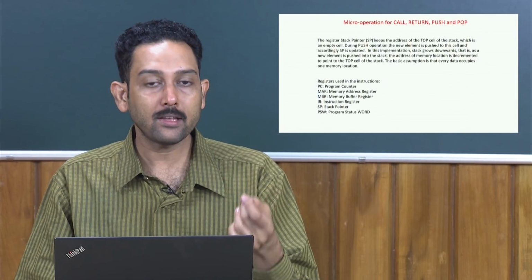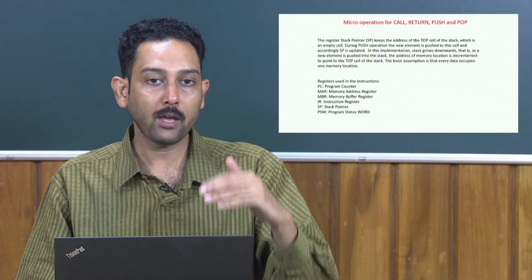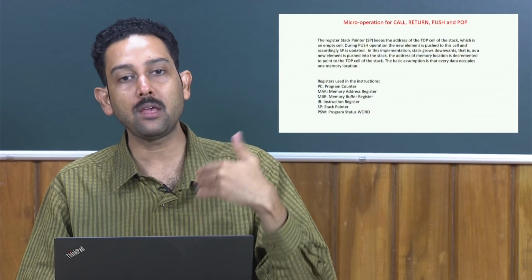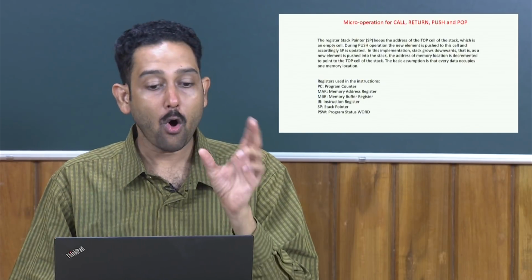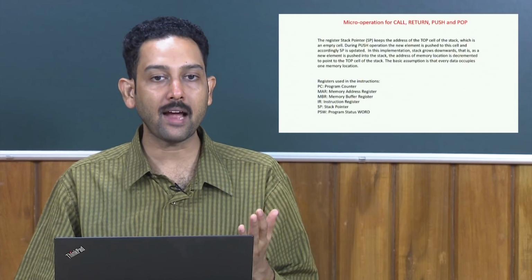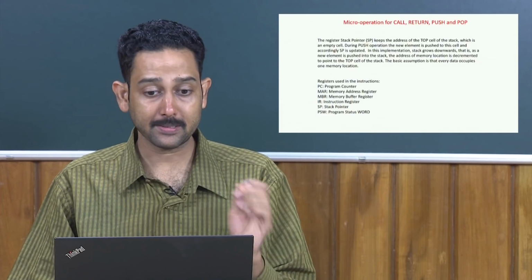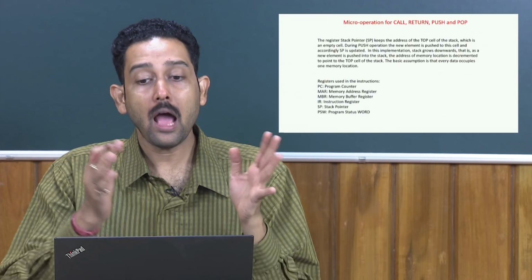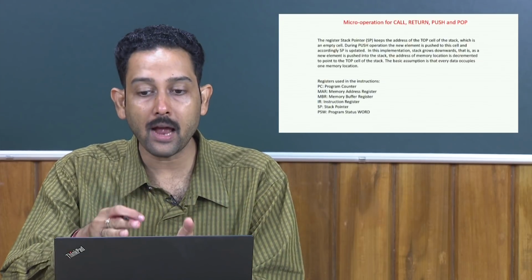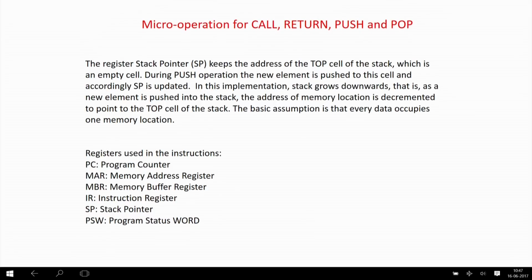If you want to call, then before you call, you have to push many values into the stack, and then you have to jump unconditionally to a place. So, all these push, pop, call and return will have some kind of micro instructions or micro operations. Now we will see how call, return, push and pop are implemented at a micro level.